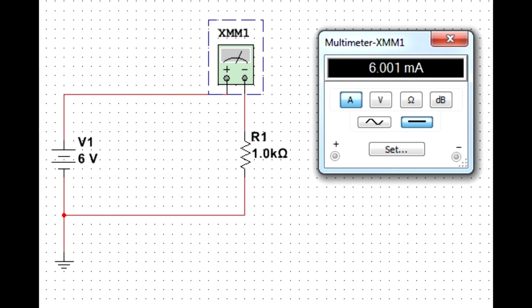In this picture we have the ammeter correctly installed. To do this you must break the circuit and install the ammeter within the system where you broke the circuit. The ammeter is most commonly incorrectly put into the system by placing it directly across from, say, in this case, the resistor. This is wrong because in the case of the ammeter you have to pass the current through the ammeter to get the reading of the current.